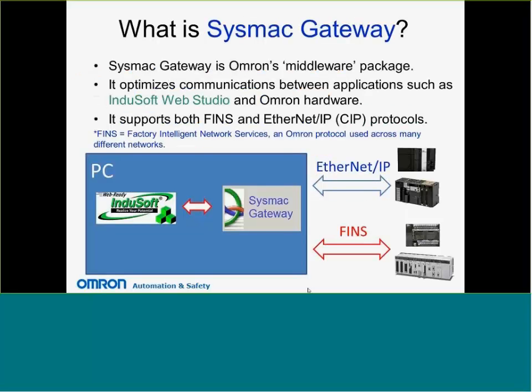So let's talk about what SYSMAC Gateway is. SYSMAC Gateway is InduSoft's middleware software package, and it was specifically designed for exactly what we're using it for with InduSoft Web Studio. It literally is a gateway into the world of SYSMAC, and SYSMAC is kind of an Omron branding of products. It optimizes the communications between applications like InduSoft Web Studio and the Omron hardware. And it does support both FINS and Ethernet IP, which is a CIP protocol.